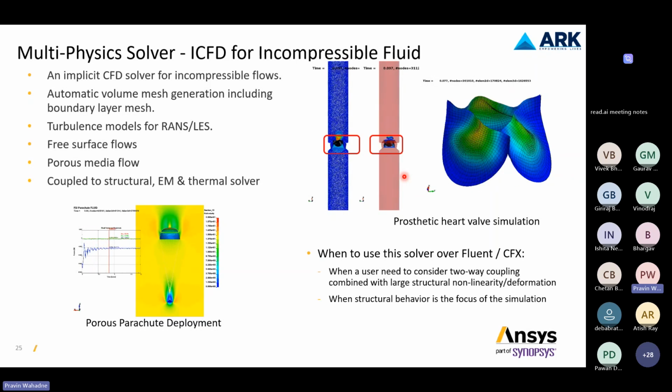So this solver basically can be used over Fluent and CFX. But when a user needs to consider two-way coupling combined with large structural deformation and nonlinearities, or when structural behavior is the focus of the simulation, then you can go over Fluent and other tools with LS-DYNA multiphysics ICFD simulation.